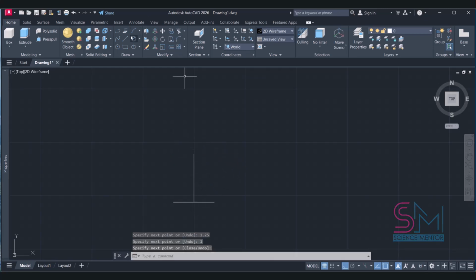The width at the base of the tooth is 2 millimeters, while the thickness at the pitch circle is roughly 1.571 millimeters. You need to be precise when drawing this part. As shown, I use both the line and scale commands to get it right. The tip width of the tooth is 1.2 millimeters, which means 0.6 millimeters on each side.